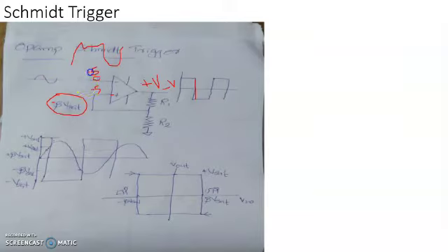When it becomes minus 5, in the very next moment, this goes below minus 5. Say this voltage becomes minus 5.1, while this is minus 5. So the voltage at the non-inverting terminal is bigger. Since the voltage at the non-inverting terminal exceeds, the output will be switching to plus V saturation, and this goes on.